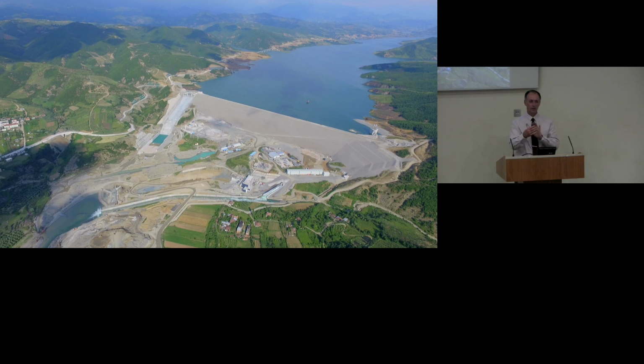What they did with the thickness of the shotcrete, I can't remember, but there's a reasonable range. In some places, you got to the point where the material was almost like a soil, and then you had to decide what you were going to do. You're either going to just remove it, as it's not rocky enough even to rock bolt. So at that point, you'd have to come up with a different solution, which we did in some places.